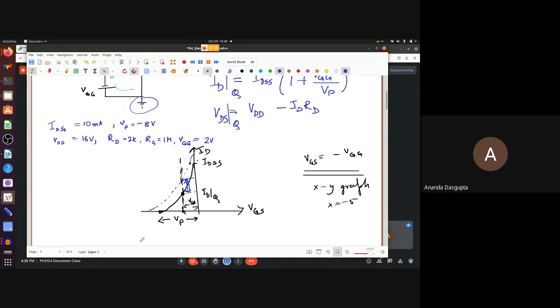Okay, so this is really not that great as far as bias stability is concerned. If you change your device, which you may have to, or even if your device just grows old and its parameters drift with time, you will have quite a large shift in the quiescent point value, and such a large shift that it might really make the circuit unworkable.